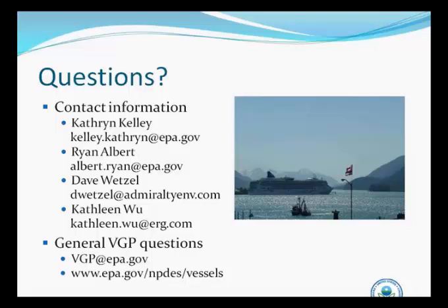I mentioned that the 1664 method is more prevalently offered by U.S. labs. The other thing to consider is definitely the hold time. The 1664 method has a 28-day hold time, whereas the ISO method has a 4-day hold time. So if you're unable to find a lab close to the dock you'll be at, I would definitely go with the 1664 so you have adequate time to ship the samples and still meet the hold time. Great. Thank you.